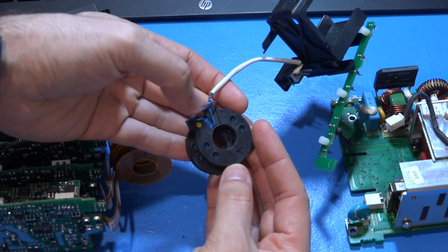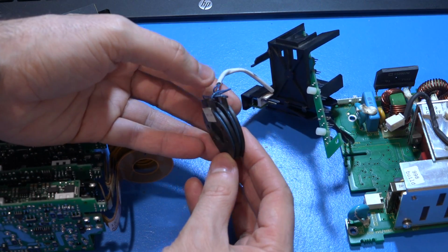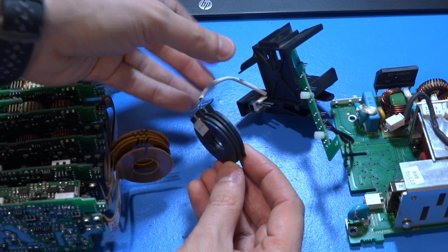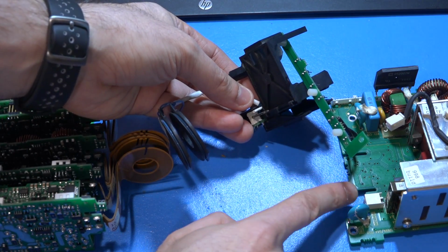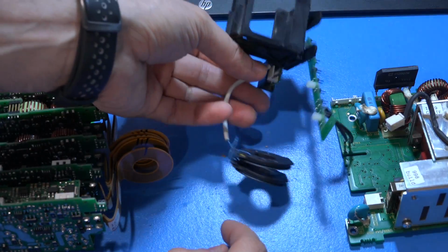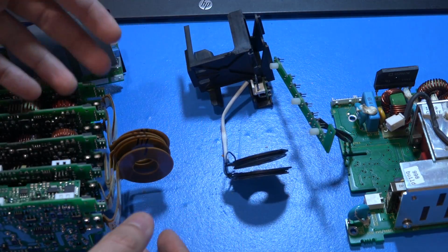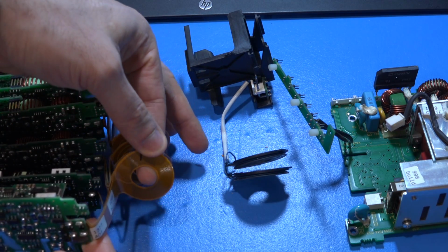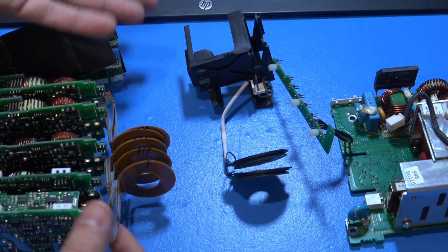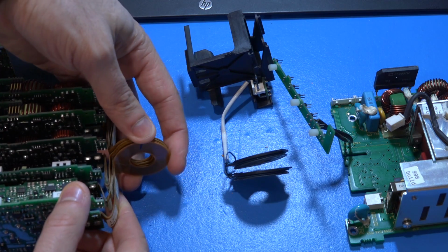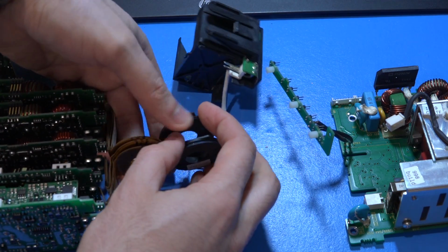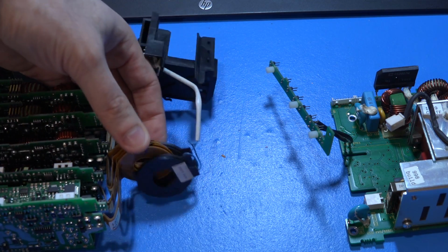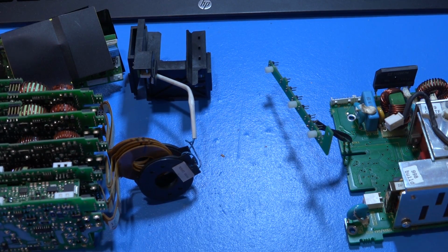You can see it's made of much thicker cable, and you can have as many turns basically as you want. In this particular case, we've got two discs which are in series, driven by this connector right here, which connects to this connector over here. So the primary side is made of this. Now the secondary side is made of ribbon cables with discs of copper on them. Basically, it's ribbon cables with very thick copper, which you can bunch up together and sandwich between the secondary, and then primary like this. So then that way you have actual magnetic coupling between the two of them.